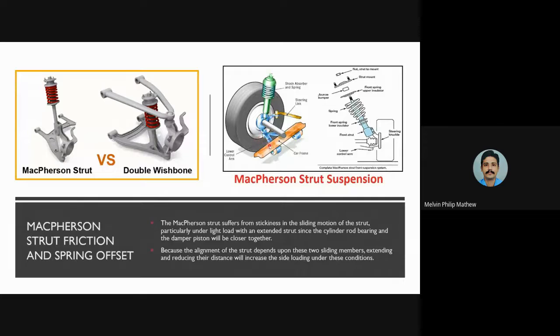So it will bend a little in the downward direction to absorb loads coming onto the car frame, to prevent any damage to the car frame, also known as the chassis. So the chassis is mounted on the lower control arm while the body is resting on the shock absorber or the spring of the Macpherson strut suspension.